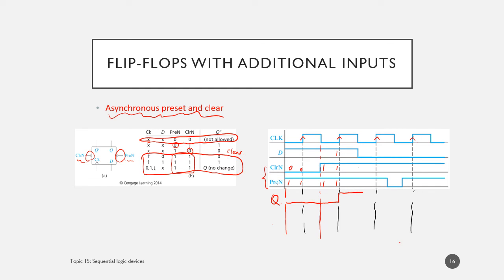And because these two values are not changing during this period, the output will also not change. So at the next edge, we still got a 1, 1 here, no problem, but D equals 0, so Q needs to go back to 0. And we need to be careful that at this moment, the asynchronous input changed again. So it changed to 1 and 0.